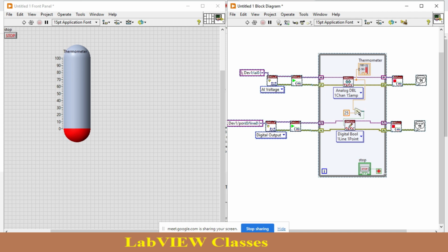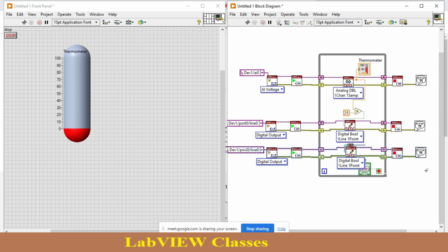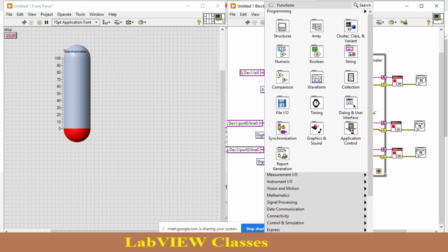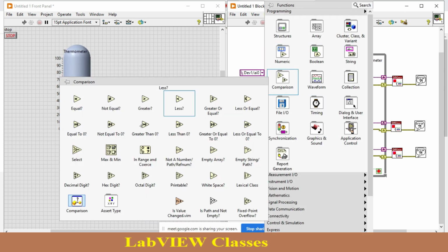So again, let's say right now it is 25 degrees Celsius. You just copy this one again and generate another signal for another pin. Let's say pin number 1. And over here in that case you just need to put a different condition. Let's say I copy this one, and over here the temperature should be between 20 to 25 degrees Celsius. It is up to you. You can change this temperature in between, also in the running program.